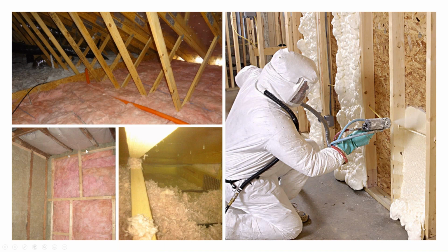Insulation, these are different types of insulation. You've got blown in insulation, you've got batting. And if you have ever seen the Pink Panther on the insulation, it actually has the instructions printed on there. The paper is supposed to go up against the sheathing or the flooring, not the other way around. So this is the proper way to install it. The brown paper is on the floor, the pink is exposed, same within the walls. And this guy's blowing in that insulation that expands.